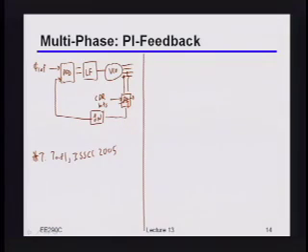Turns out there's one more trick you can play that gives you the same effect of doing this phase interpolation, but at least conceptually doesn't require you to have the high-speed hardware. Or at least, maybe it's just another way of building the same thing. So, anybody take a guess? What else could you possibly do to introduce a phase offset into the PLL, basically by blending between multiple phases, but not necessarily doing it at the full speed of those clocks? Any thoughts?